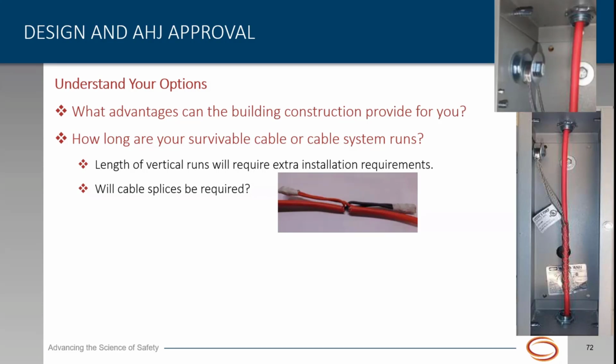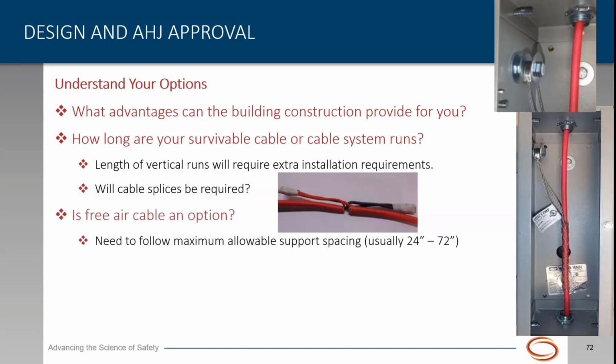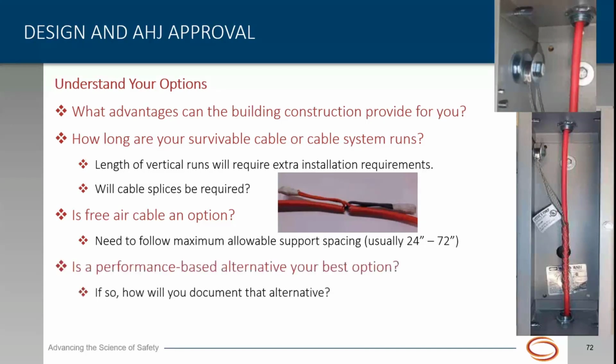Also, will cable splices be required? You do not want to have to splice survivable cable in the field. You've got to trust me on that. But you need to know the very unique requirements there. Is free air cable an option? Sometimes it is, but note that the support spacing may be quite a bit different than what you're used to. Sometimes it's as little as every 24 inches it has to be supported, and with a specific type of hanger. So you've got to look at those requirements.